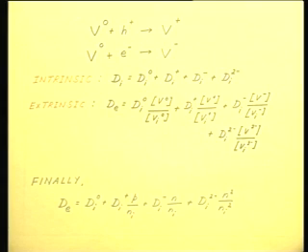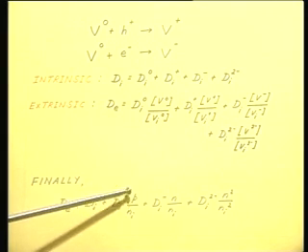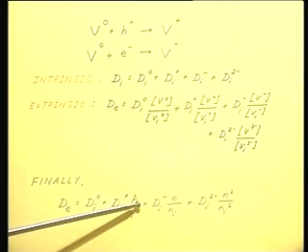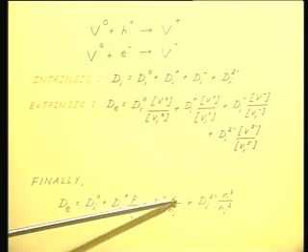So, for a general case, what do you see? You see that the effective diffusion coefficient, the extrinsic effective diffusion coefficient contains a number of terms, and depending on which term is going to dominate, we have either d equal to constant, the first term which is not dependent on the concentration, or d is proportional to the concentration, depending on whether you have an acceptor like impurity or a donor like impurity.